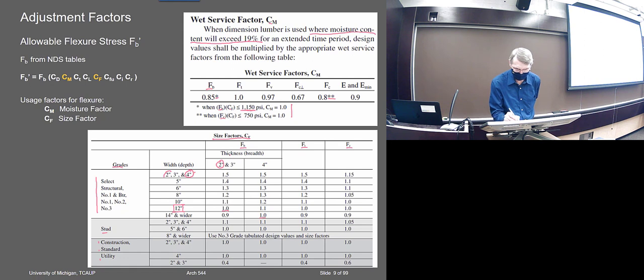All right, so the nomenclature gets a little bit tricky. Normally we think of thickness as depth, but that's not what they're calling thickness. They're calling thickness the smaller dimension, or the breadth. That's why they specify breadth, so you understand it's usually that way in a beam. So that's the 2 or the 4 inch, and then this is the depth here. So you can kind of tell. You just have to be a little bit careful with these ones where they have 4 and 4.